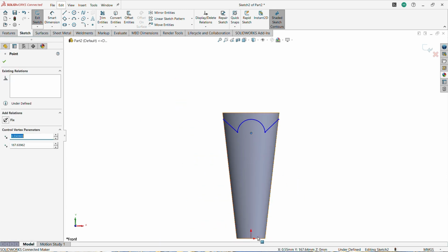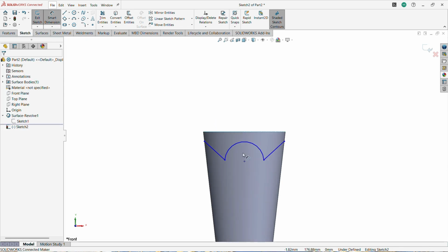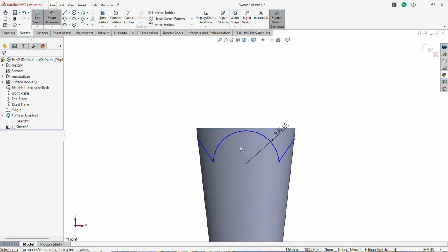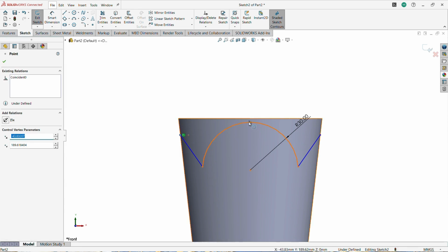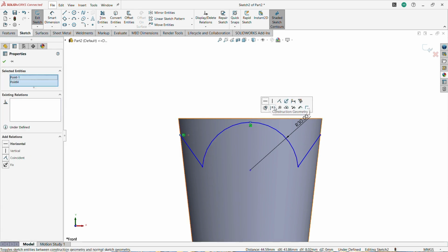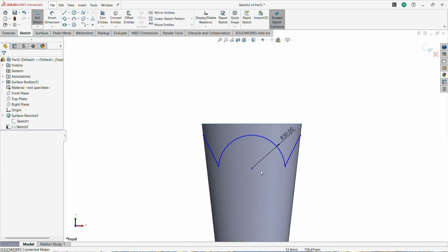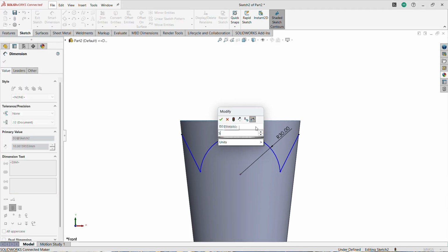Now select this end point as well as an origin point to fix it linearly using vertical constraints. Now use a dimension to fix this profile at 30 mm. Once we mention that, again I am going to pick this top end point, select it as well as this midpoint as well as the other end point. Now fix it linearly using horizontal constraints. Afterwards, the exact dimension we need to pick from this area is the top end positioning dimension.